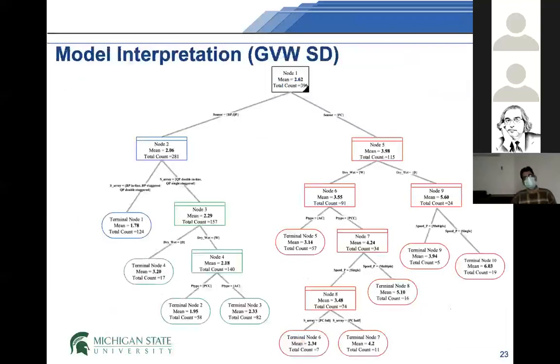Now, I just want to go over this decision tree based on the data. If you want highly accurate data, you should go to a bending plate or quad piezo. And if you need more accurate data, you need to have a staggered sensor array. In this case, your bias will be even less. But if you go to other sensor arrays, you can have slightly higher bias. If you are in a dry or wet region, in a wet region we have seen the accuracy is better. Then on AC pavement, the bias will be more, and if it is on PCC pavement, the bias will be less.